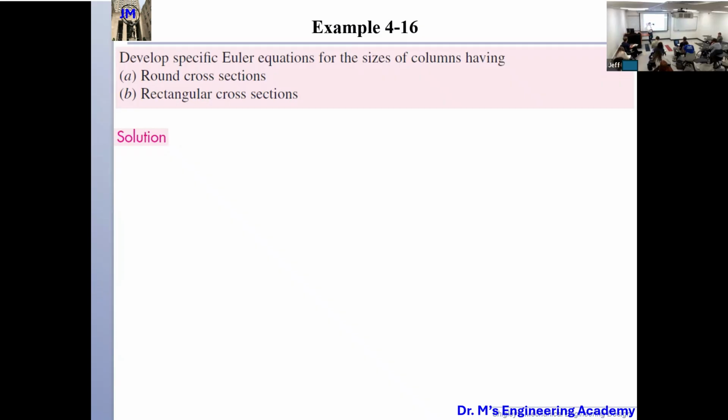Look at my cell phone. I love it very much. Take its icon, this cross-section area. If I compress it, and I don't want to break it, can somebody tell me how this will lose stability? In which direction? It will go this way, okay? You agree? It will lose stability this way instead of this way. That is because B is much higher than H.